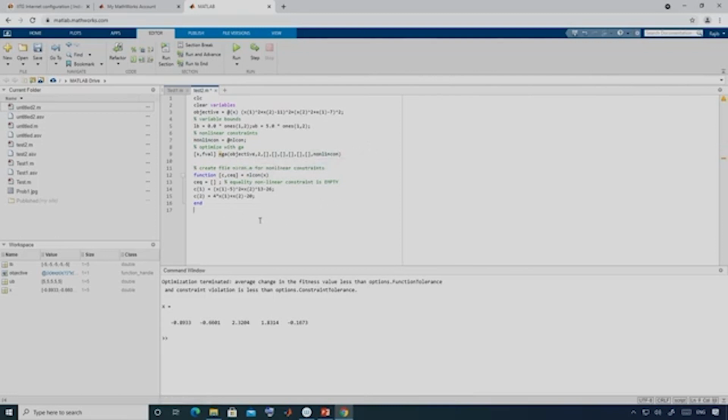So, I am removing it. So, here you just see we do not have any equality constraint. So, this is empty and we have 2 inequality constraints. So, that I am putting C1 and C2. So, after that I am running this particular line in order to get the solution, and then the x value and the objective function value at the optimal solution you will get.